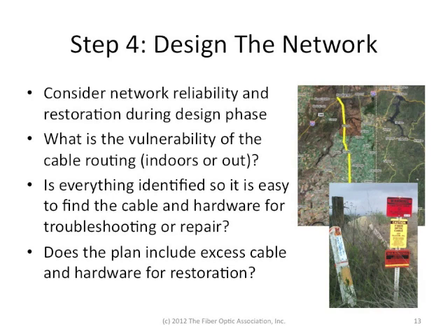Does the design plan include excess cable and hardware for restoration? That's one of the things you need to plan from the beginning. You always buy extra components, store them away, along with drawings of the cable plant, so you'll have them available for troubleshooting and restoration when a problem arises.